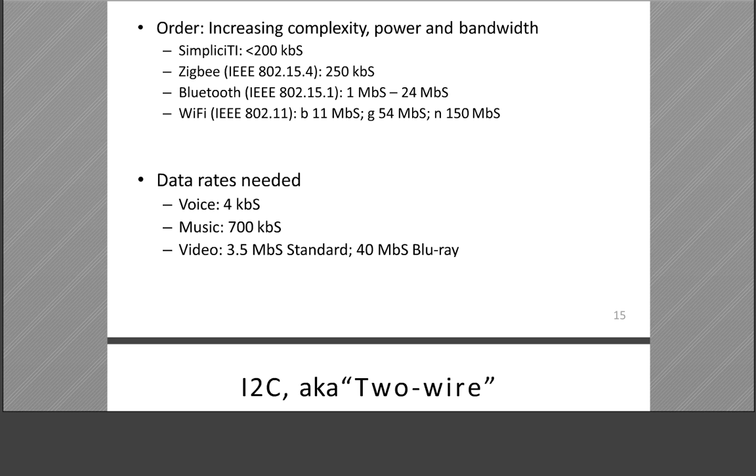That's right. Nyquist says the rate of sampling in A to Ds must be greater than twice, multiplied by 2, the maximum frequency of the input signal, the analog signal.